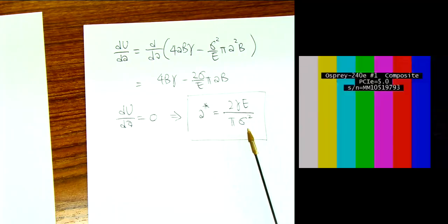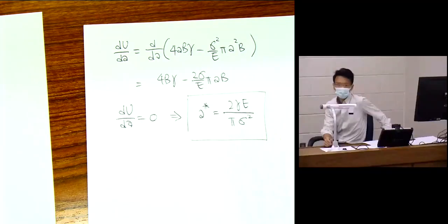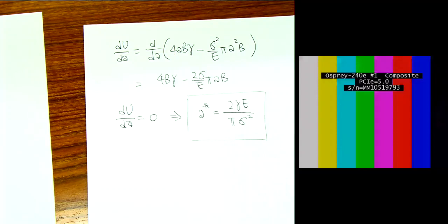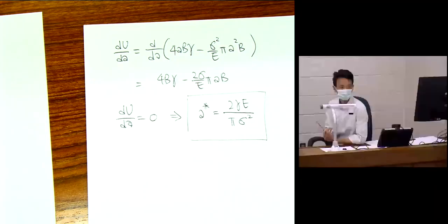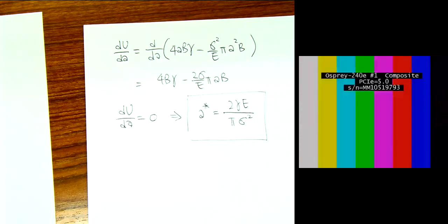Now, stress is what is being applied. So if you know what you're applying, a certain amount of stress, and you want to know whether this is going to crack, let's calculate the critical crack size for that stress, and I just make sure that the crack size is smaller than that A star.